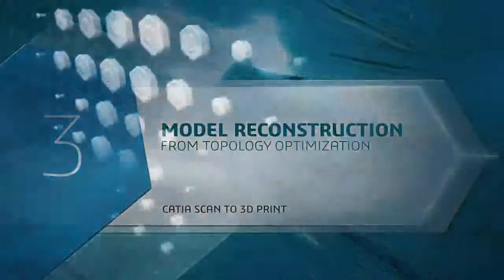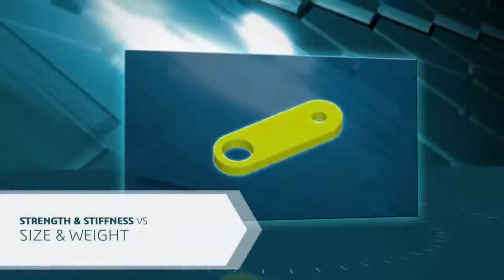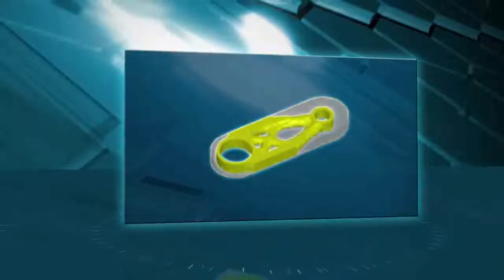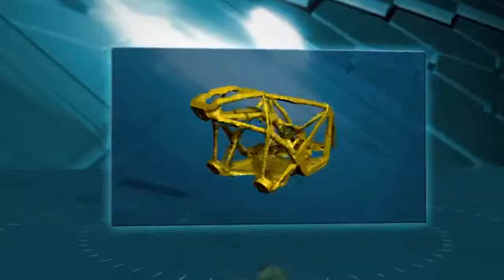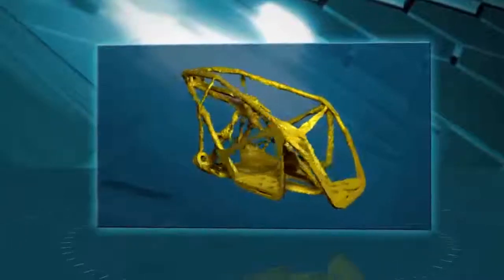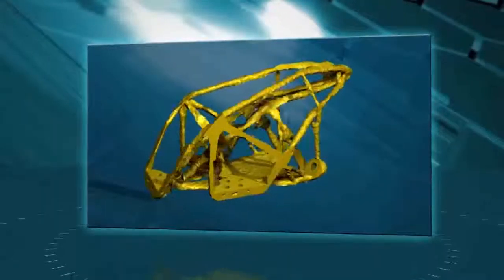When designing a product, there's always a trade-off between performance requirements for strength and stiffness versus size and weight. Recently, tools have become available to help in optimizing a part's topology, like Simulia Tosca, for example. The result is a very organic shape, which can be produced using 3D printing. There would be no chance with conventional manufacturing methods.